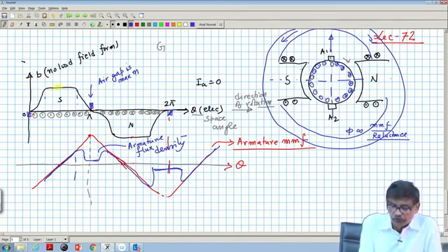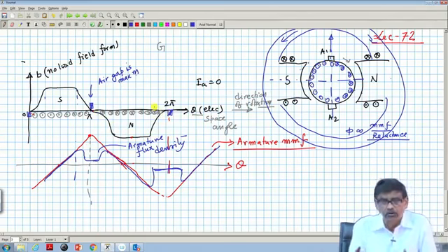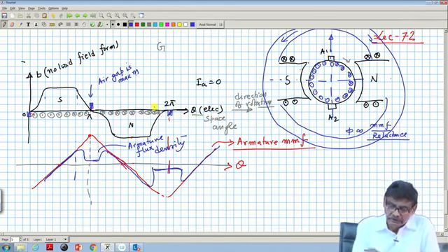This was the no load field form when I A is 0, that will always be there individually. When armature current is not present, this is the only field present: the B distribution, the flux density at different space positions in the air gap. Then when the armature is loaded, it will carry current in the same direction as that of the induced EMF. So, this I have shown.